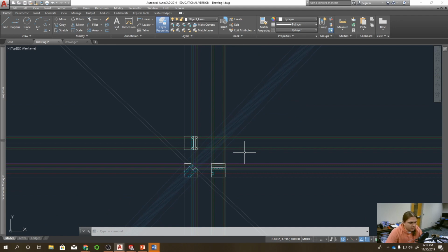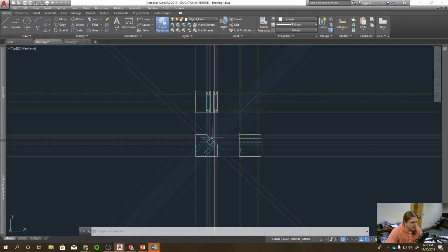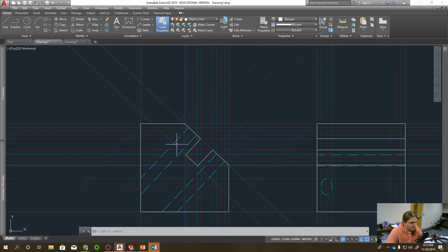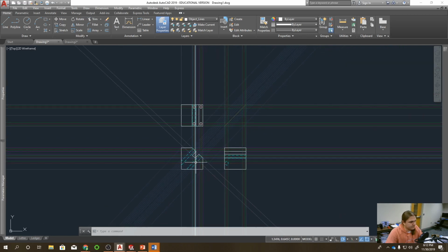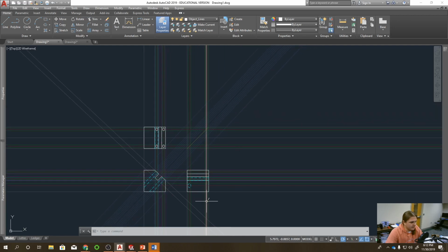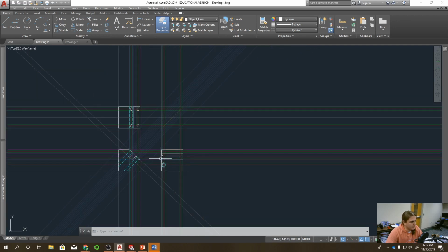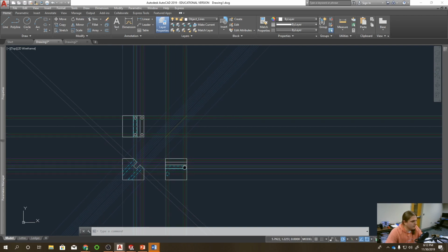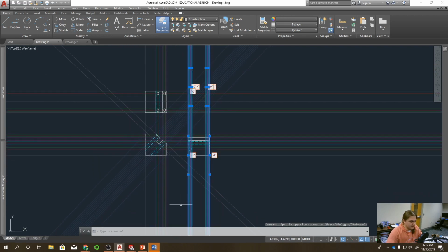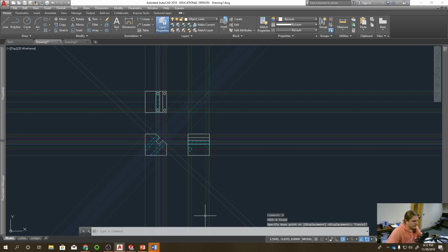So now the auxiliary view, I am projecting lines perpendicular to the plane that I want to be looking at. And so that gives me all those sizes. And then the other thing I need now is just my depth of the part, which I can get from either my top or right view. I'm going to use my right view. I'm going to move these lines for my widths. I'm going to actually copy them.